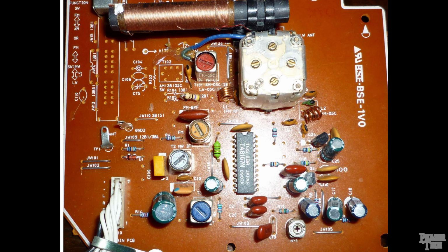In audio and radio equipment, you'll likely see all types of caps on the circuit. In the power filtering sections, you'll probably find electrolytics and ceramics. But in the sections where the audio signal passes through, you'll likely find film caps in the audio path. But for most other applications, there's no advantage to using film over ceramics.